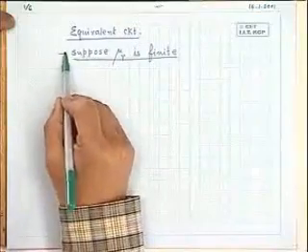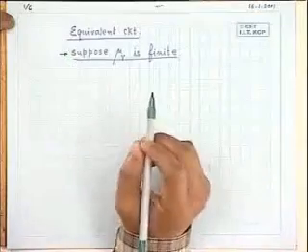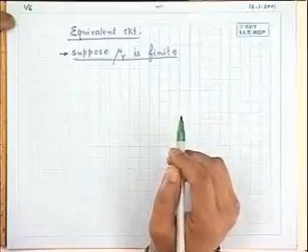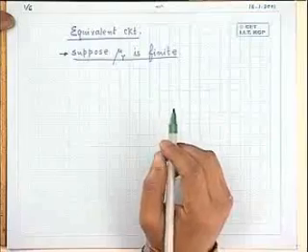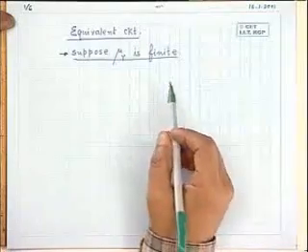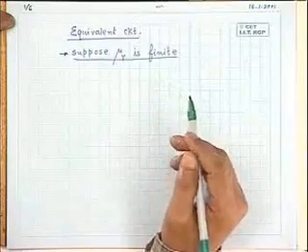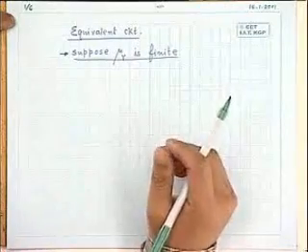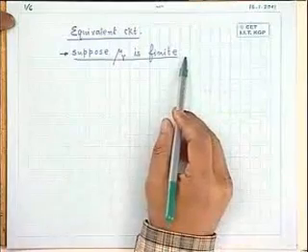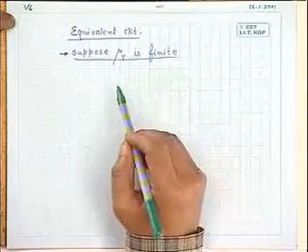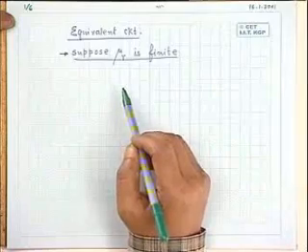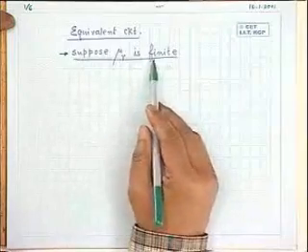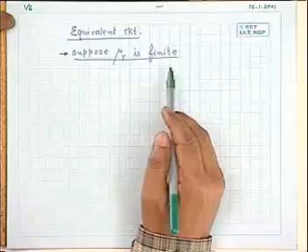Then what we started is that this ideal transformer is of course quite different from a practical transformer. In a practical transformer, for example, there will be an iron core whose permeability is finite. Winding resistance will be present. Leakage fluxes will be present. So that is called a practical transformer. We are now bringing those realities into the equivalent circuit of the ideal transformer one by one. So we first decided how to tackle the situation if mu r is finite.